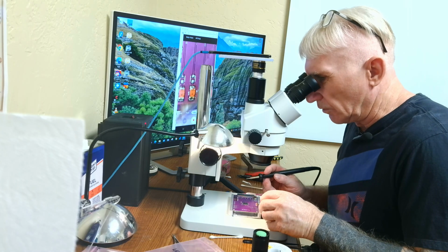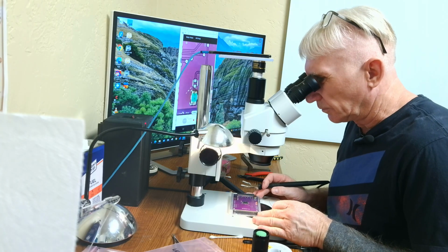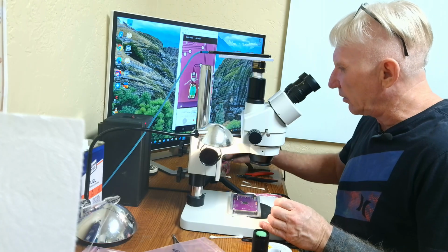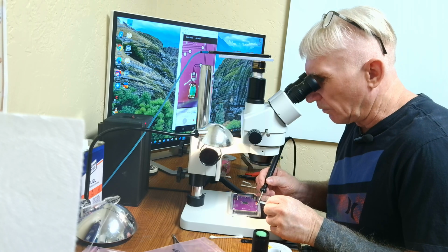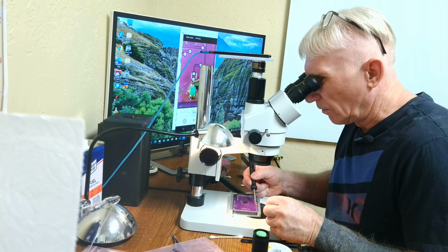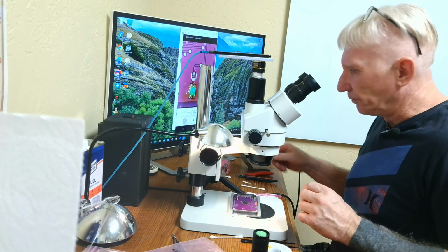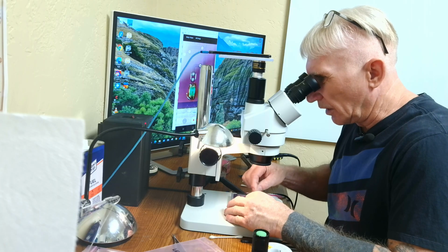All right, I don't have too much flux down on this end. All right. Yeah, stirring up and shaking up my flux, making it thicker, and cleaning my tip, it just totally changed the way we're soldering here. But it's doing okay. That ought to work. Looks okay. So let's hit it with some alcohol before it gets crusty and hard to clean.